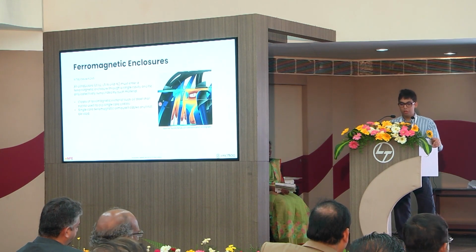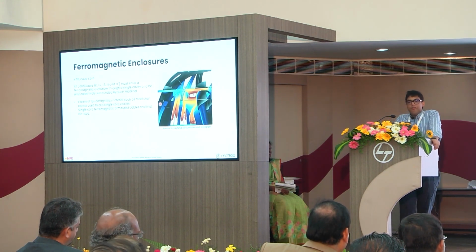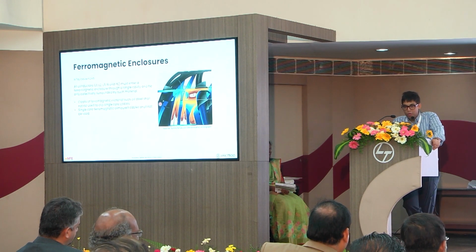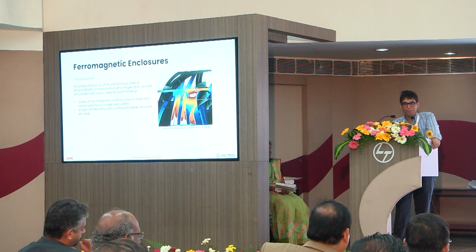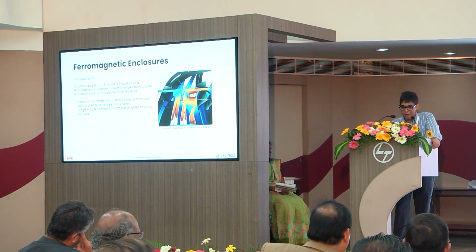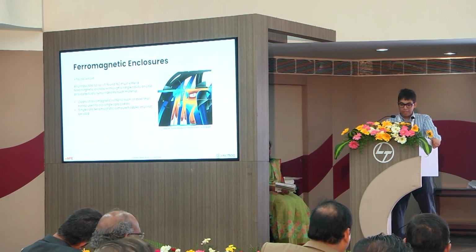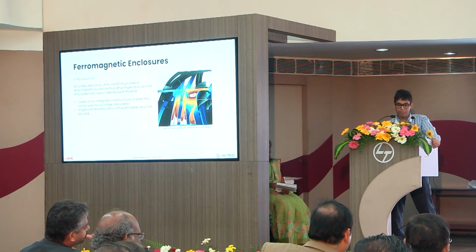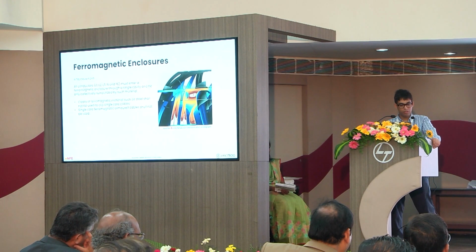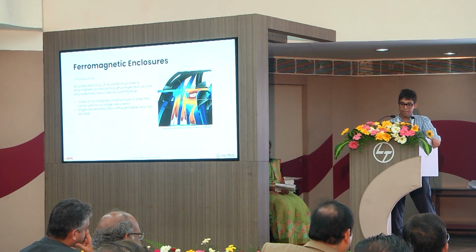Ferromagnetic enclosures. Now this is an interesting one. We've all seen the meter board, we've all seen distribution boards and things like this where you have cable entering through. I'm sure we have, right? But did you know that this is actually an image that a friend of mine, David Watts in the UK, shared. You've got 2 parallel conductors for L1, L2, and L3. And between L1, L2, and L3, there is a ferromagnetic enclosure. And see what's happening there.